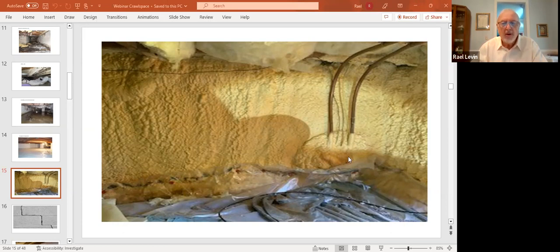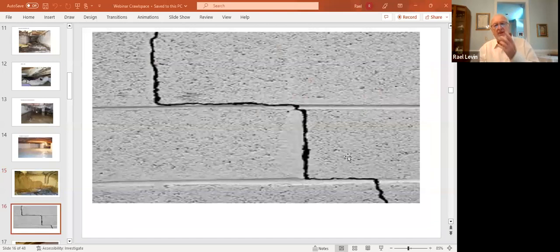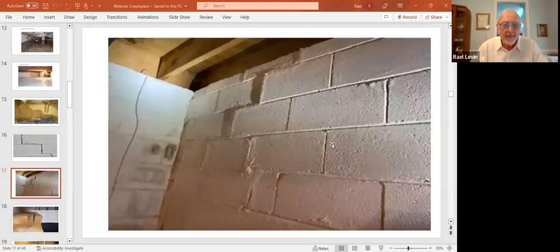So we're also concerned about cracks in the foundation. You see this is called a stair-step crack, and we've got more than a 1/4 inch here. In actual fact, we see some movement in this particular foundation. The stair-step crack is pretty common, usually found in areas where there is a little bit of settling. And in this particular picture, you can see that the actual masonry block is moving here.